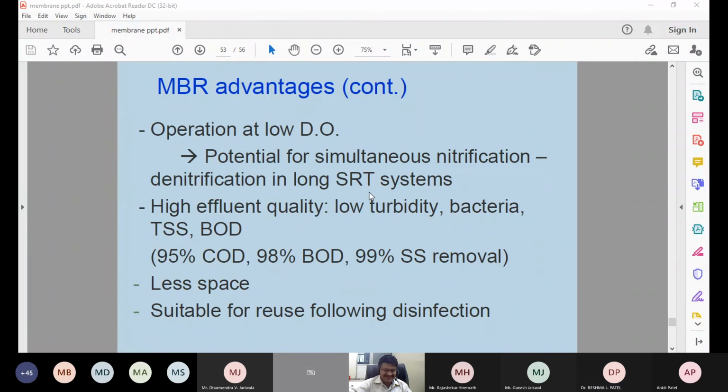Yes, this is research now also. If you see on the internet, it is not clarified how much TDS you should reach. But due to taste problems, if it is more than 700, people just use the RO system so that it becomes around 100. Many people I have seen are using the RO system for river water source, and if you drink that water it has no taste. It becomes nearly 0 TDS. So that is not good.